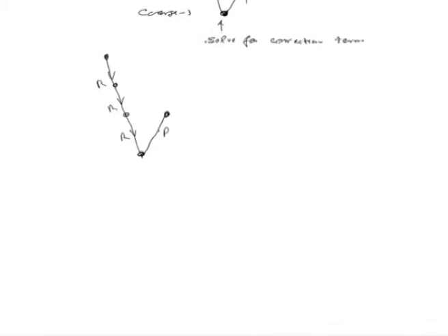But instead of proceeding all the way to the top of the hierarchy, we might proceed only to an intermediate level, and further we would obtain a certain residual here. We would repeat the process, go back to coarser and coarser grid levels, solve for the correction vector once again, and then do the final set of prolongations to reach our finest grid level. So this is the finest grid level.